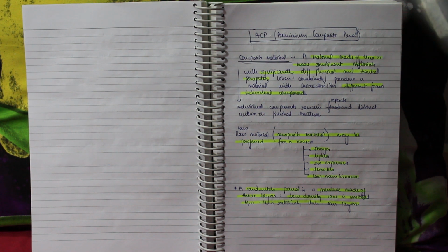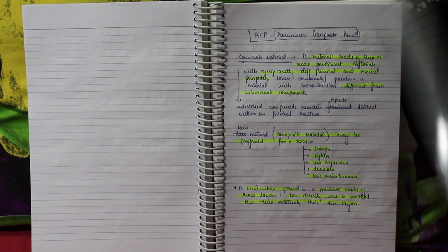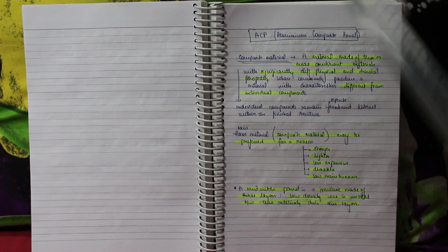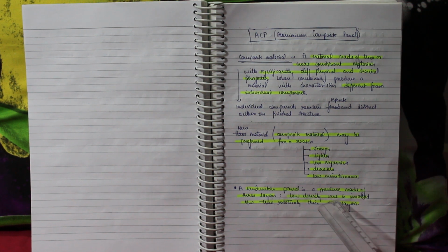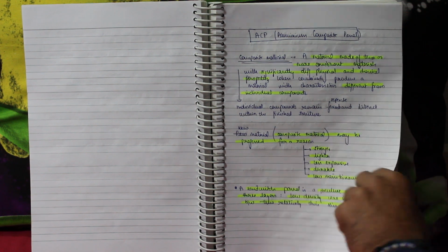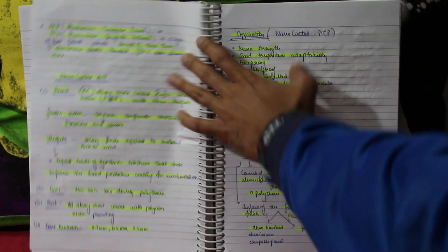So what are ACPs? ACP is a sandwich panel. What is a sandwich panel? Like we eat sandwiches, it is a three-layer device. ACP is a three-layer device wherein the structure is made in three layers: a low density core inserted in between, with two thin skin layers at the end. One is at the top and the other one is at the bottom.